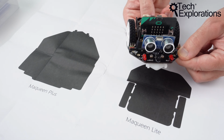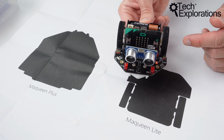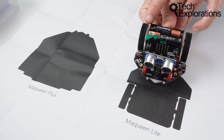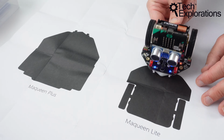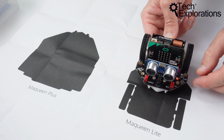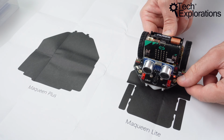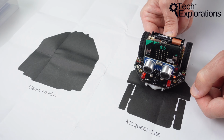First, turn on your Maqueen. I have already uploaded the line following example program, and the way to do this is, because the wheels are spinning, I'm just going to hold my Maqueen a little bit over the surface and make sure that the two sensors, this one and this one, are right over the black area. So then press the line key and hold it. This is the button right here. Press and hold until you see the blue LEDs blinking. Then let it go, and that's it.